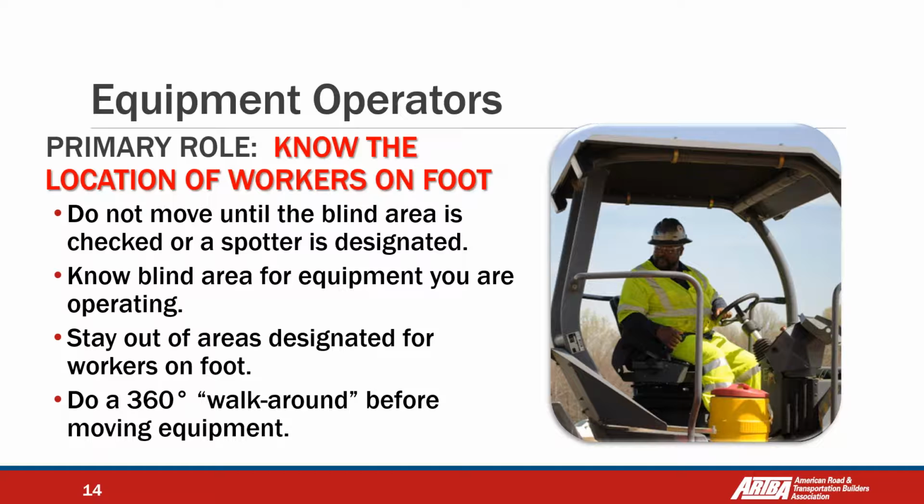The problem here is that we are talking not only about horizontal problems, but also vertical problems like power lines and underground utilities, where sometimes they are doing excavations and all these things. They need additional assistance, especially from spotters, to control the operations. So some recommendations: don't move until the blind area is checked or a spotter is designated. No blind areas for equipment you are operating.